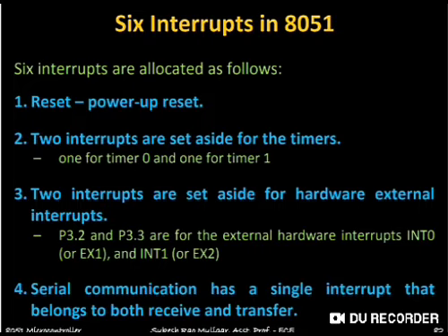In the 8051 microcontroller, there are 6 interrupts. The first interrupt is reset. Reset can generally be treated as an interrupt, even though there is no return and no interrupt service routine, but the mechanism is similar to an interrupt. Apart from this, there are 5 more interrupts.